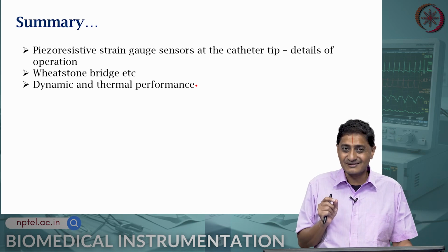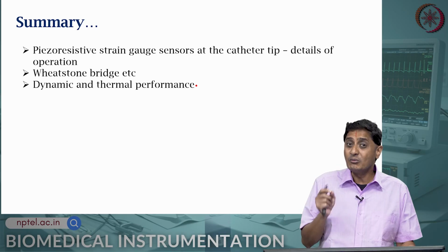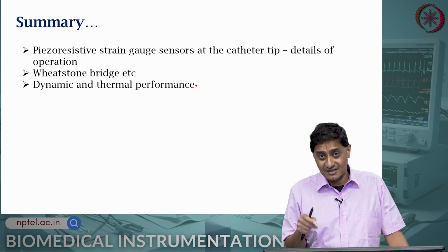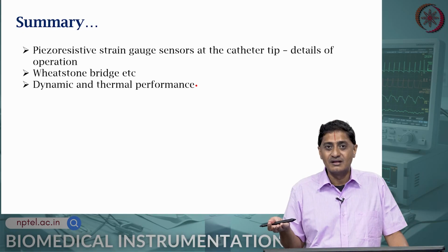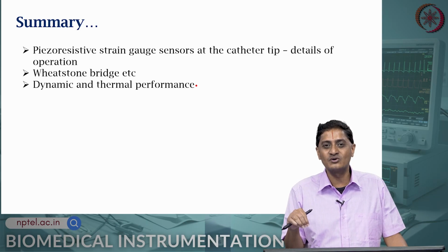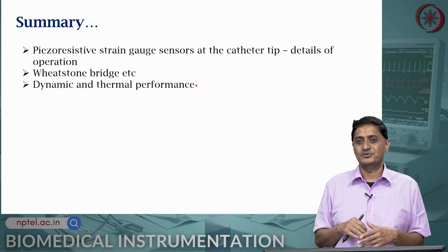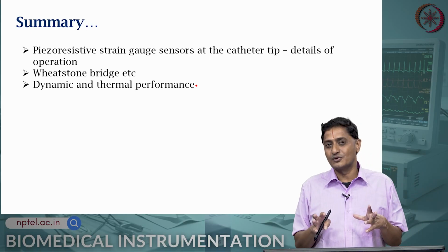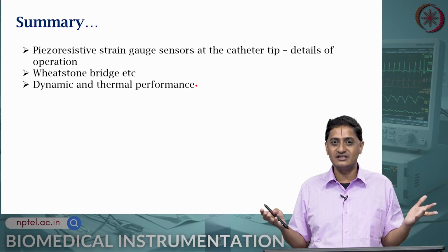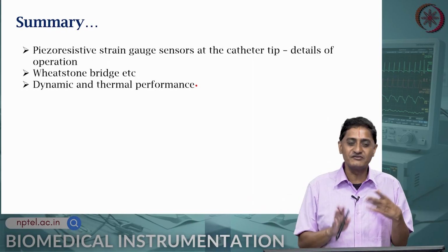So, that is a critical constraint, because silicon strain gauges, being made of silicon, have material properties that add more constraints to the design. So, you cannot have everything. You cannot have durability and sensitivity and high SNR and high fidelity and low cost, all of these are not possible.